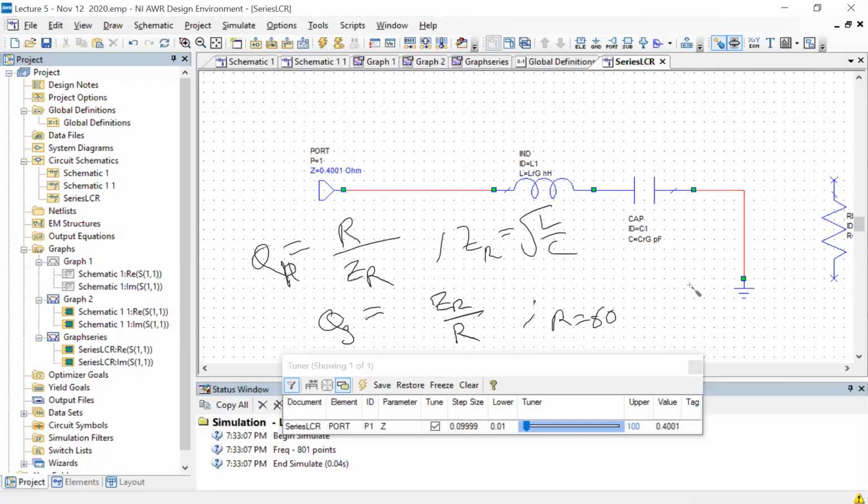Okay, so this was just to complete the story of parallel versus series. Remember again that all of this constraint is coming from the fact that we have to work at these high frequencies, where the characteristic impedance of your transmission line and the ports cannot be very different from 50 ohms. Also, the values of L and C have to be within a typical range for them to behave properly. And that is the constraint.